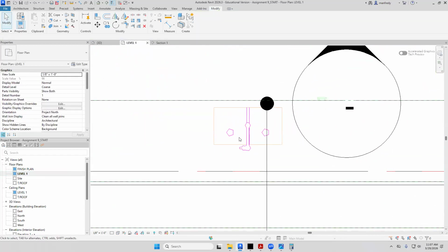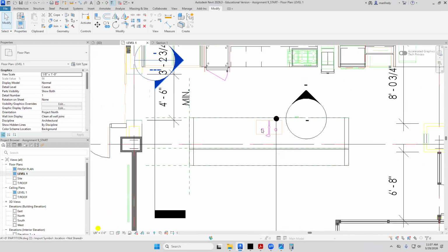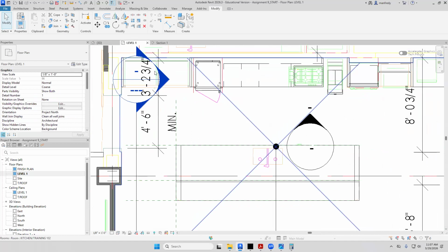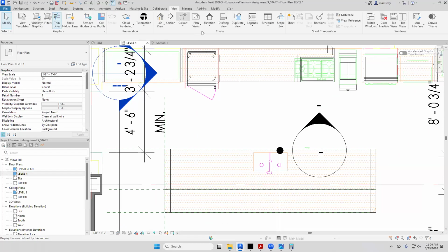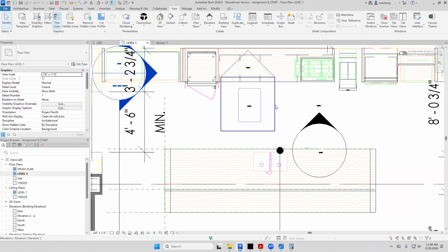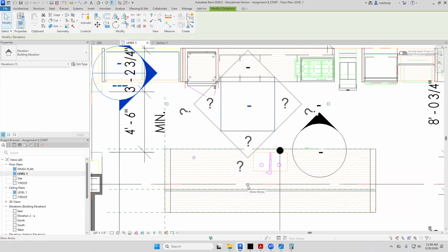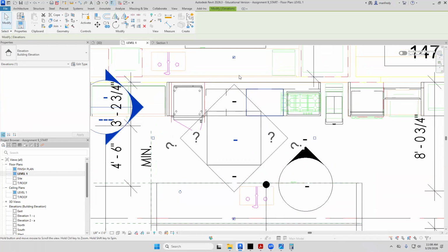This has a sink here, an opening for a sink. And if I take a look at an elevation, I would probably want to draw another elevation tag. I'll draw a view elevation tag looking down. So I'll put it here. I'll click on this and point down with the little checkbox. So now this is turned on. This one's turned off. Turn that off.